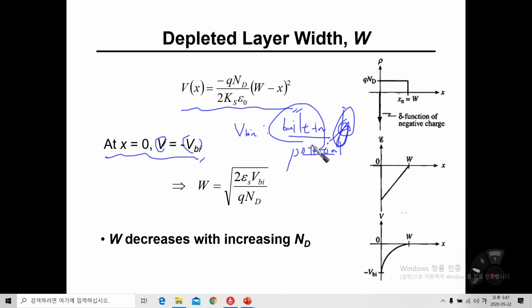Yes, doping, donors. Because donor atoms have one more electron compared with the silicon atom. So the donor atom would become ionized. In other words, it's going to lose its fifth electron. However, the ionized dopant atoms are tightly bonded with the four neighboring silicon atoms, so they cannot move at all. But electrons coming from the donor atom can become movable.